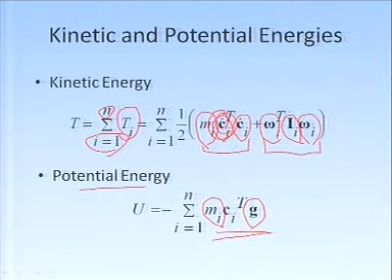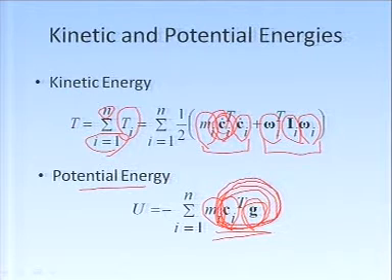So, the projection of the mass center along g will give you the potential energy, which is very similar to what we learned in our earlier undergraduate classes, called mgh: mass times acceleration due to gravity times height. Here that height term comes from c_i transpose g, which gives you the gh term, and the negative sign is there because we are assuming gravity is acting in the negative z direction. So, we are writing it as negative one.